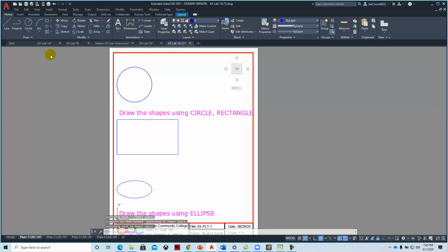So we can go to the circle command and then we can just click in a spot here next to it. Since this one's already here kind of as an example, I'm just going to move it over to the right and then go up a couple of clicks and draw a circle. When we create three-dimensional models, we need to have boundary shapes. So this circle is about 1 inch radius, about a 2-inch diameter. And I'll hit escape to clear out those grips.